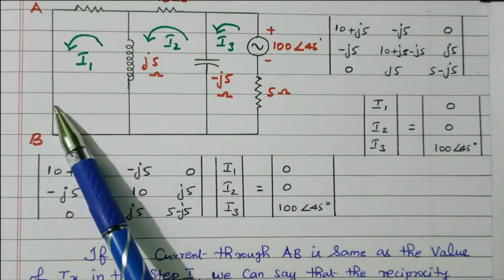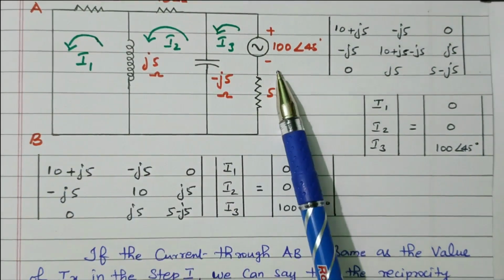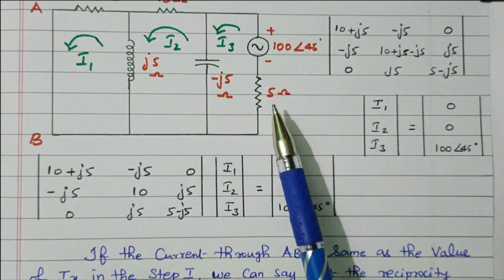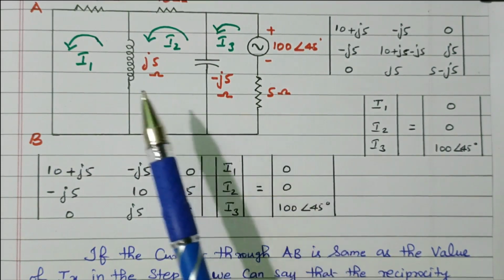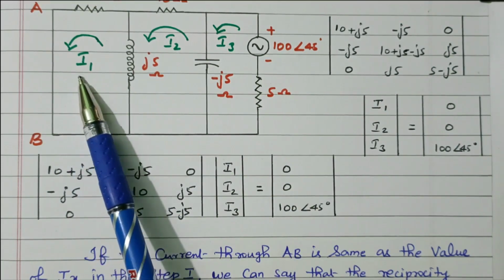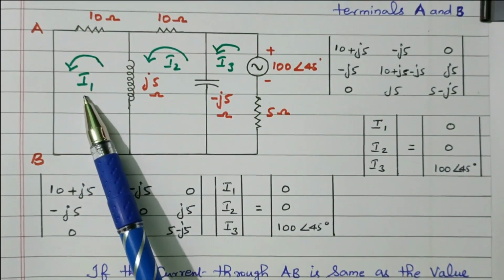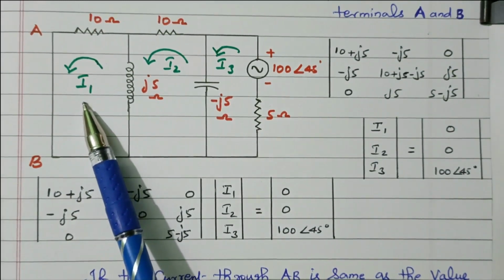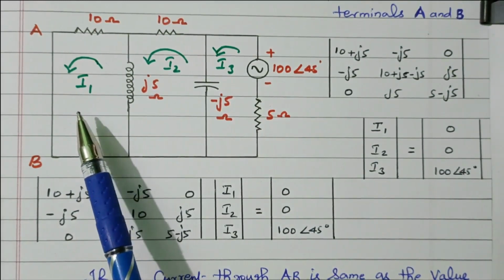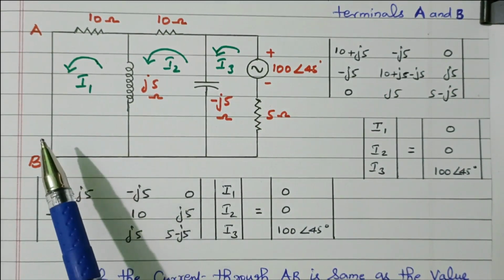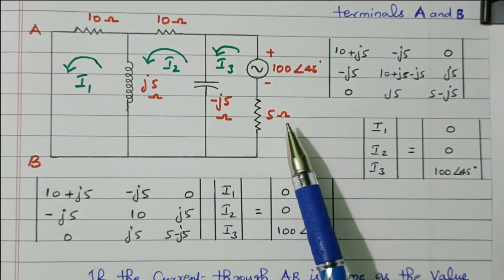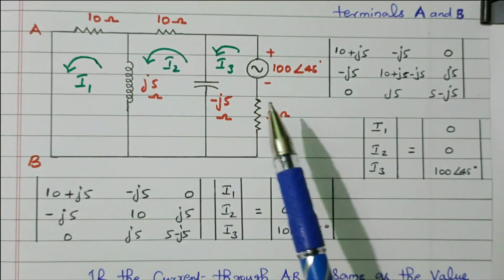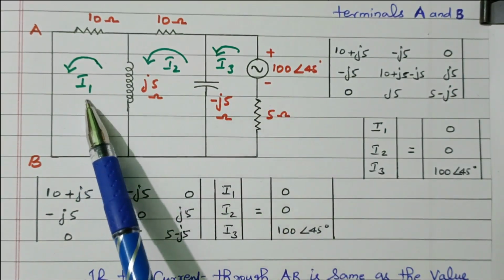Now see here, the voltage source is now transferred to the third branch. Now we need to verify that the current in the 5 ohm branch, what we calculated as Ix, should be available in the first branch, I1. The I1 should be the value we calculated, that is 2.167. Right. So the voltage source from branch 1 is transferred to branch 3. The current we calculated should now be reflected in the first branch, that is I1.